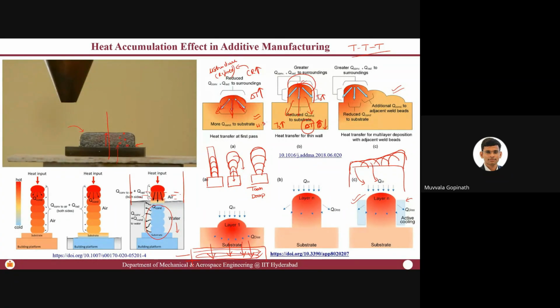All those aspects also have to be well considered. Right now, if you see this one slide, which is a collection of literature, except that video, there are a lot of methods reported in literature. But the problem is, none of these can be adopted in industry, because industry will not be happy to dip their component inside the water, and putting on active cooling or fans is not acceptable, because if you are using powder as the feedstock material, it will create its own issues. And for the substrate, fine, if you use active cooling up to this height, it may be able to solve the issue, but what happens beyond that is not in control again.